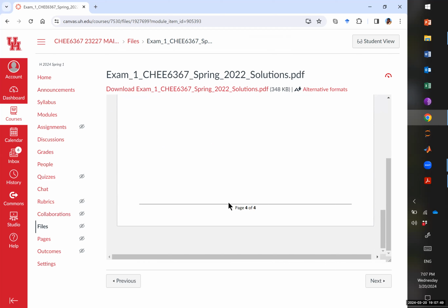There is more in the paper that shows you that the theory can guide you to determining what the engineers figured out heuristically, which is, let me take the average height and use that as my control variable. Go figure, why on earth is the average a good idea? Well, it's because it has more mass and that's a slower system, and it doesn't let any of the three tanks oscillate violently. So what the heck, it should work, and it does work. Interesting. The theory corroborates that indeed. Okay, thank you.